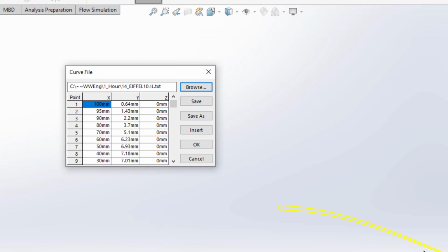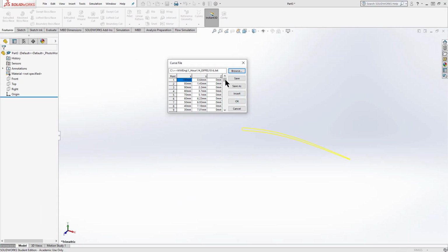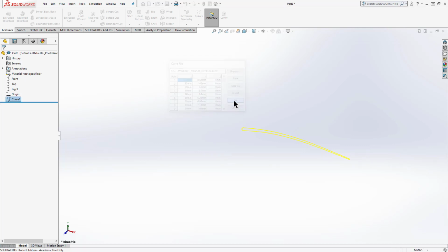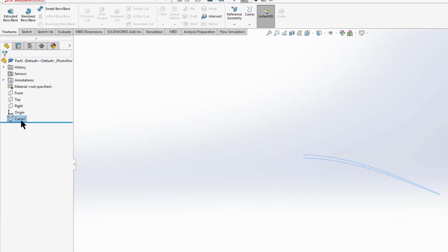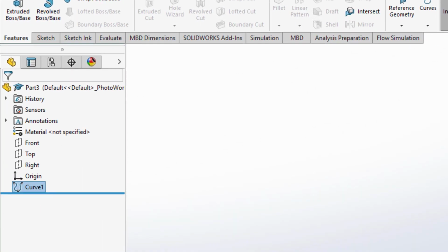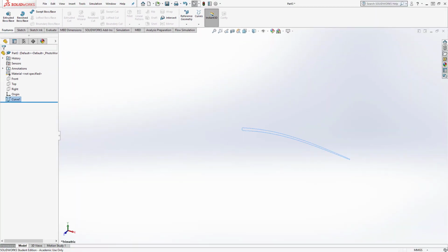As soon as I open it, notice what I get over here in yellow, where my cursor's flashing. I see the profile that these points define. So there's my profile that my points define. If that profile does not appear, it means your file's corrupt and it won't work. It can't interpret it. So this tells you, hey, this is what I'm going to bring in. Simply click OK. And I've brought curve 1 into the file. I'll go ahead and pause it for now, and we'll pick it up when we start an extrusion.